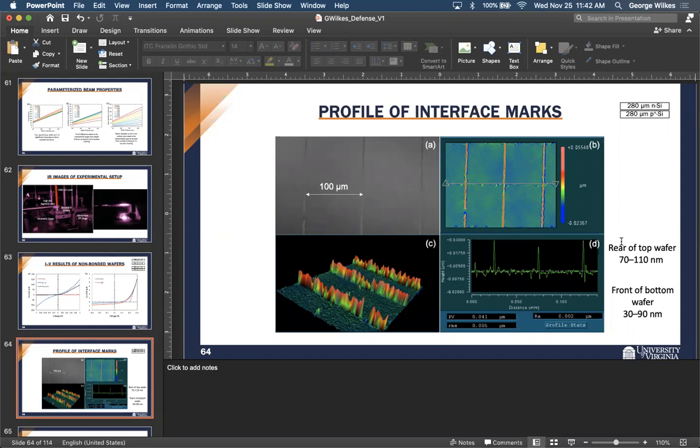It'd really be helpful to see the interface with TEM, do a cross section at the interface between the two. Yeah. So the goal would be really to completely bond both pieces, right? Basically not having overlapping lines where you scan your laser. Something like that. Or maybe, as Professor Lee was saying, use a defocused beam in a huge spot at a very high power to sort of fuse the two together. That might work as well.